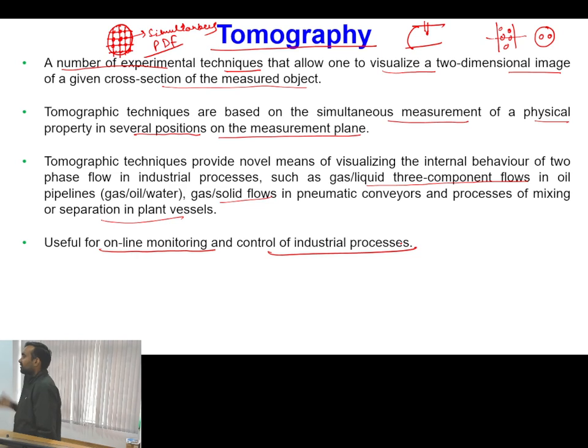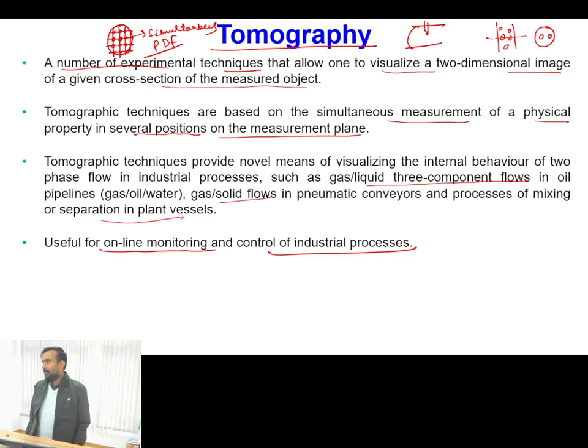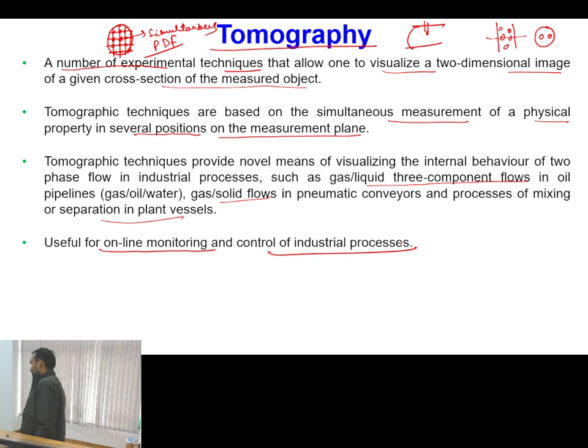Even in the case of, say, coal-based thermal power plants, you cannot stop a thermal power plant in between, correct the problem and again switch on the power plant. Why? Because you have a large number of components and each component has its own thermal inertia. For example, if you are operating a boiler and some fault has come in the furnace of the boiler, in that scenario what will happen? You have to first stop burning the coal.